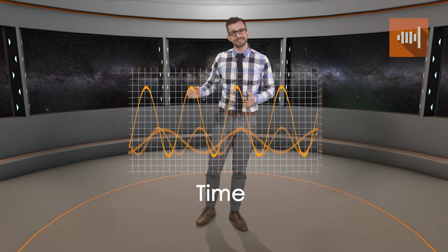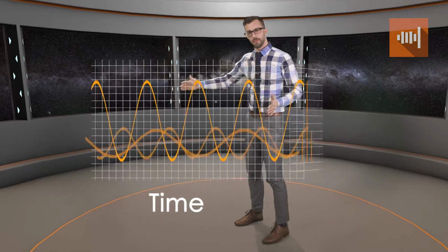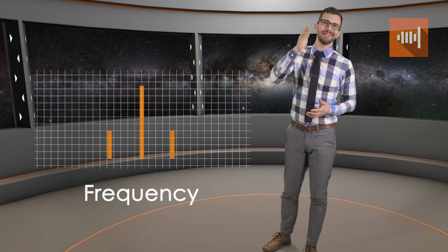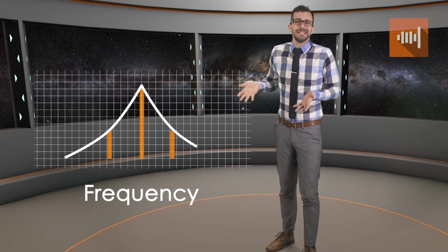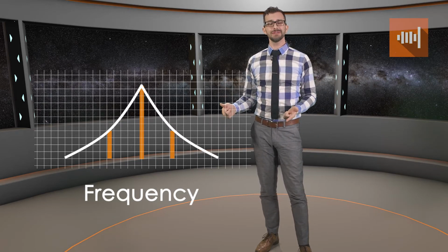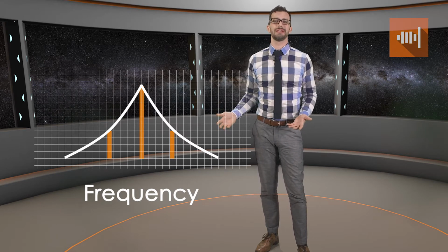So we can look at the signal in another way. If you look at this frequency, what is called the spectral density graph, it would look something like this. The frequency is represented along the x-axis, and the amplitude, or power, is represented along the y-axis. In an ideal world, the signal would be a vertical line. But in reality, the signal looks more like this. The extra unwanted areas on either side of the carrier signal, they represent phase noise.